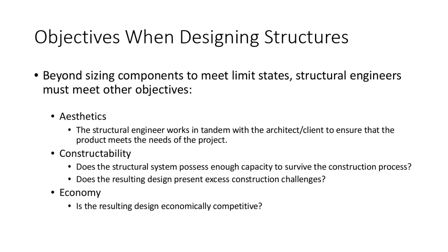One issue that tends to arise is architects tend to love open spaces, open concept. If an architect had their way, they would have columns 100 feet on center and completely open space to do whatever they want inside the building. And some of that is to meet the needs of the client, and some of that is the freedom to meet the needs of their client. But the structural engineer has to come in and say, okay, that's actually not possible. Physics won't let you proportion the building that way, because if you do, it will fall down and kill somebody. So there's some give and take.